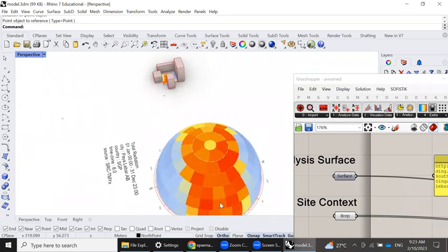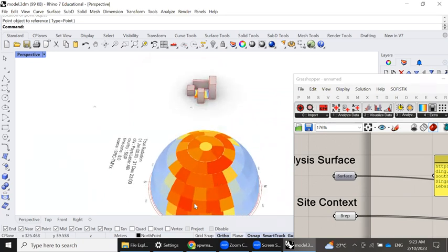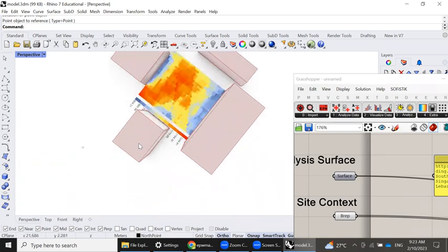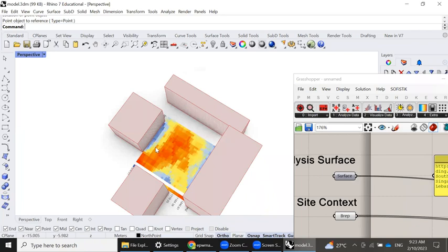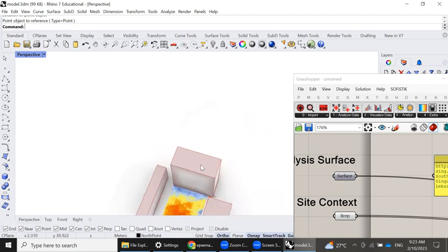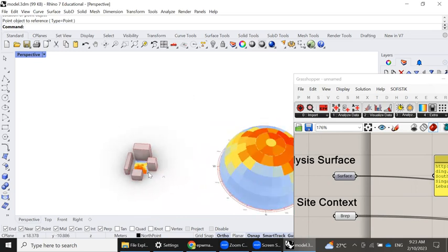In terms of the whole site for Paya Lebar, our sun is going like this. If you take a look at our radiation analysis, it's done correctly, but this building is offering some shade to this particular portion. I cannot stress how important it is, but always double check whatever you have done in your analysis. Otherwise it's rubbish in, rubbish out.